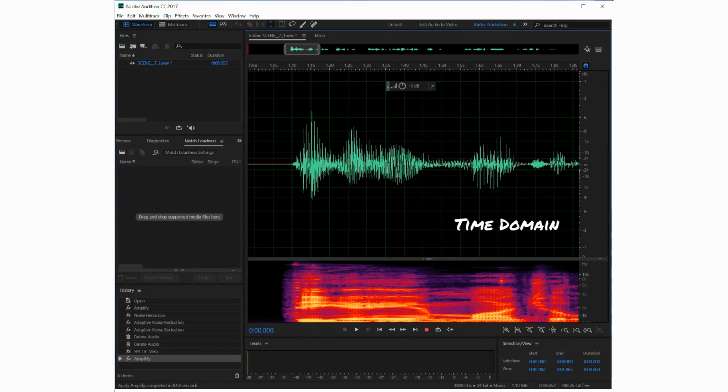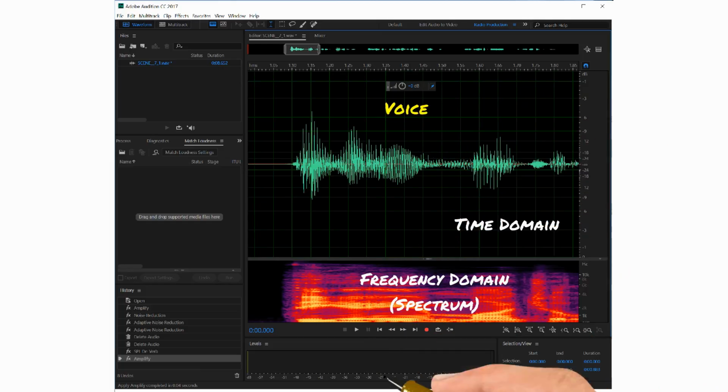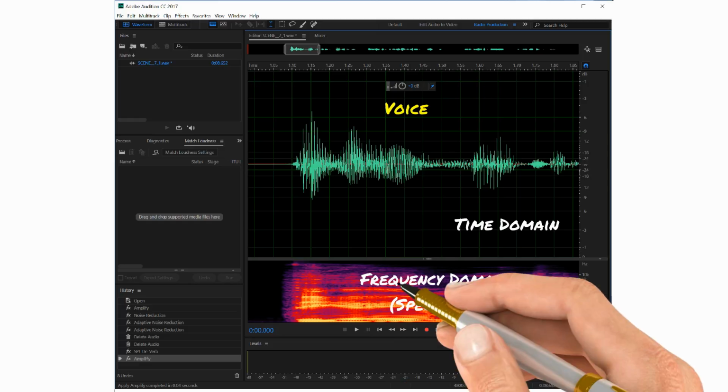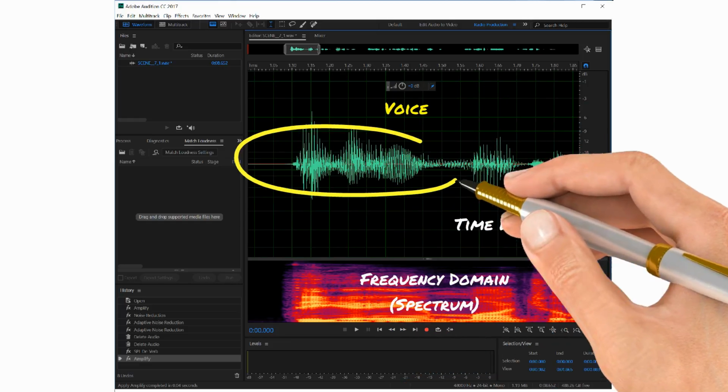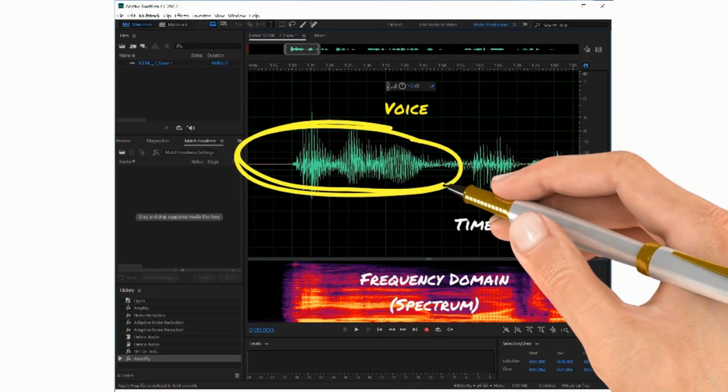An AM signal is not a continuous signal. Let's take a look at a voice signal in the time domain. When you speak into the radio microphone, the power supply needs of the transmitter ramp up over time following the audio waveform of your voice. You can see that the signal has lots of lows and highs and is not uniform. These transitions translate into the amount of power fed to your transmitter RF output amplifier. This non-uniform waveform allows the battery to ramp up the delivered power to meet the needs of the radio.